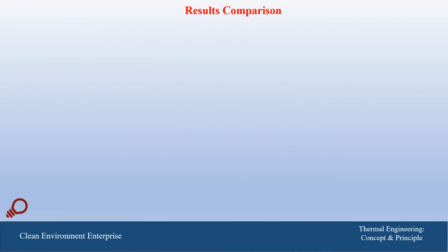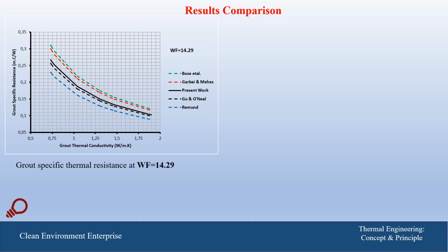After using the characteristics of the heat exchanger, the single U-tube, in different correlations which are available in the open literature, we have found that the grout specific thermal resistance varies with the thermal conductivity of the grout.